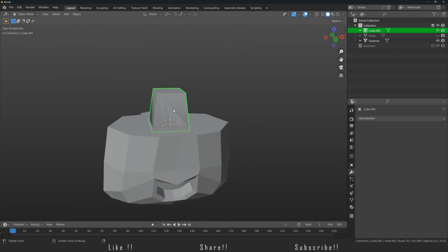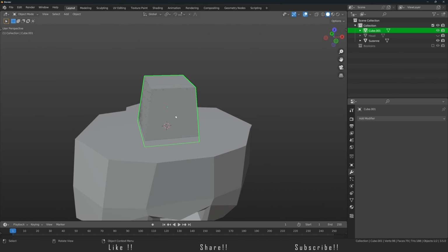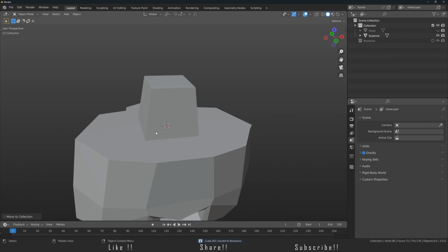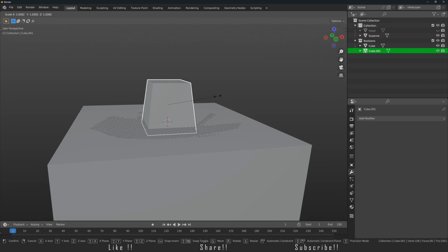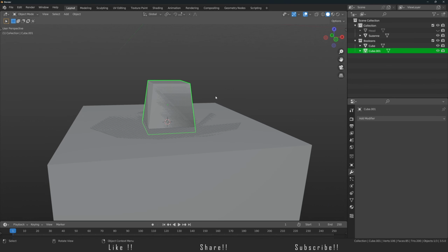So now I want you to remember that you save this key, the boolean objects, if you want. The reason is, let's just say that if you were to print this object and you realize that we have shrunk down the key a little bit too much and now it is loose. You can use this object, like this boolean object, and basically scale it up and then reprint it again so that the key could fit a little bit better. So just for the sake of adjusting the keys a little bit later, you need to make sure that you actually save the key itself.